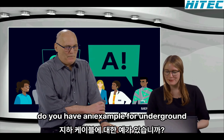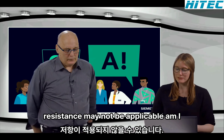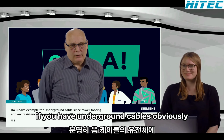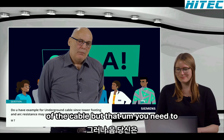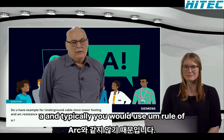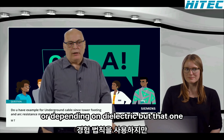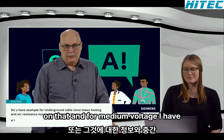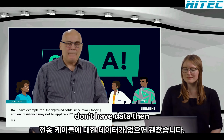Do you have an example for underground cables, since tower footing and arc resistance may not be applicable? Am I right? Of course, this would need another half an hour, I guess. Maybe you can. If you have underground cables, obviously you do get an arc in the dielectric of the cable, but you need to calculate that in a different manner, because it's not the same as the arc in air. And typically you would use a rule of thumb, a certain arc depending on dielectric, but that one has to be discussed separately. There's not that many parameters or information on that. For medium voltage, I have some data, but for transmission cables, I don't have data.